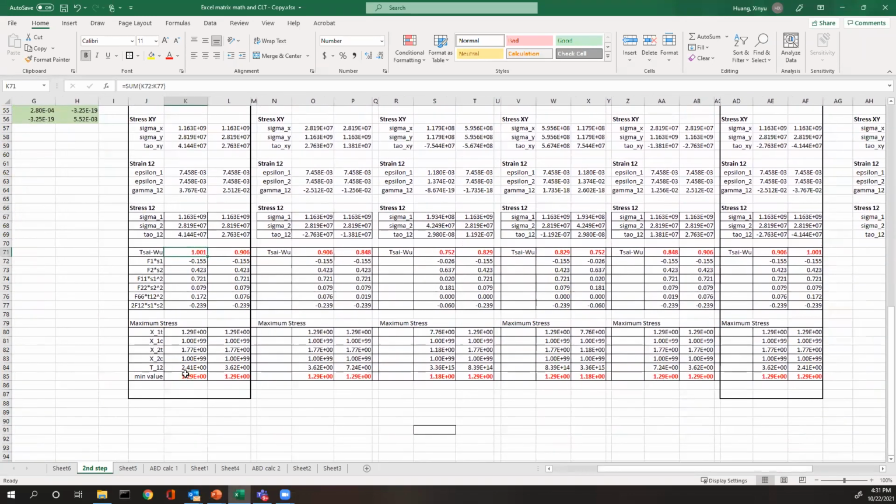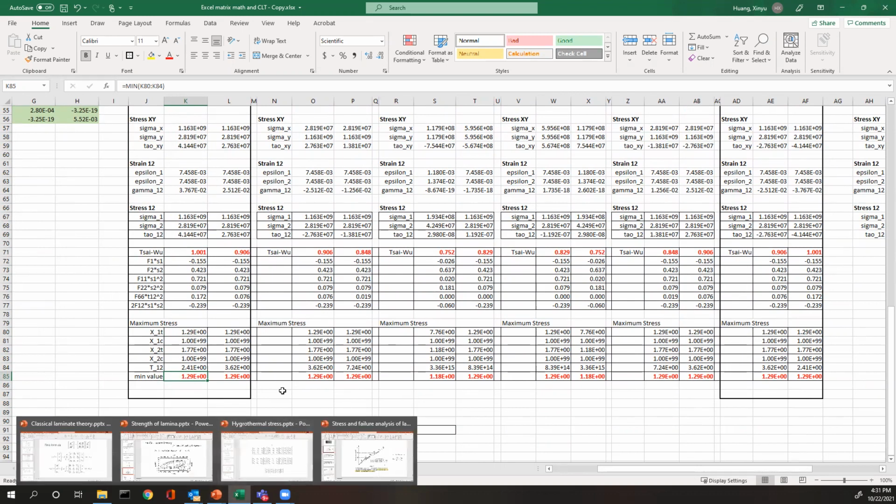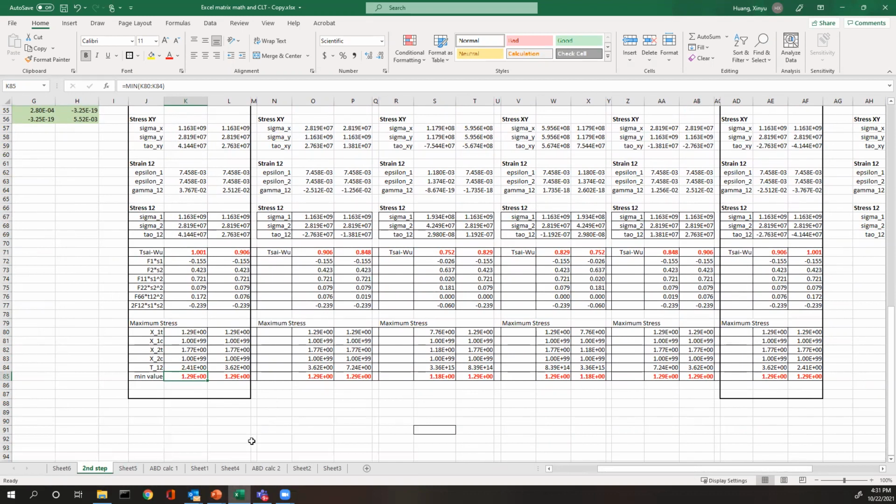All right. In this case, based on the maximum stress theory, what's high is the tensile stress in one direction. One direction tensile stress, this stress is high. So this will be the tensile failure of the fibers. So as we said before, if a fiber breaks, usually they consider the laminate broken.